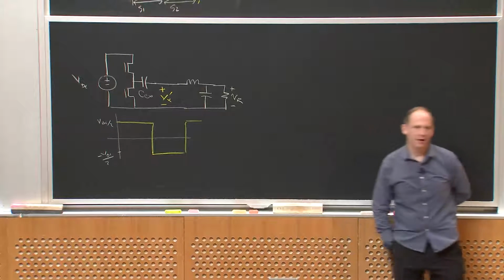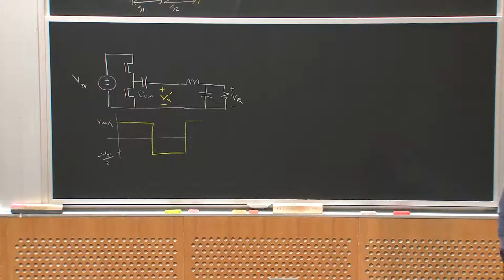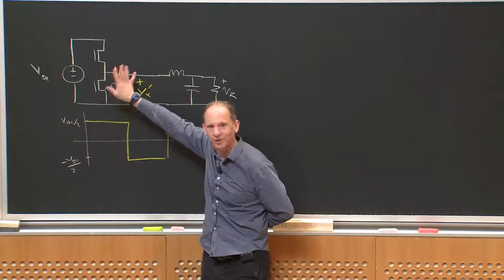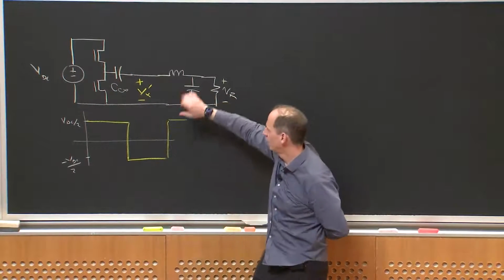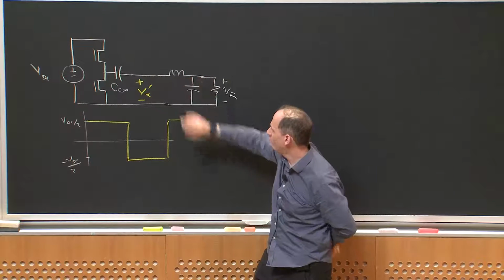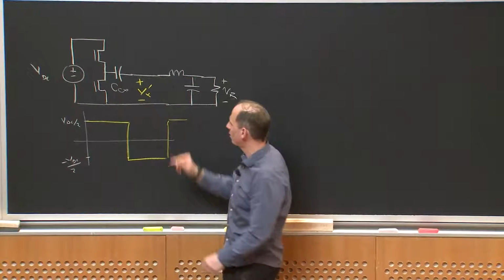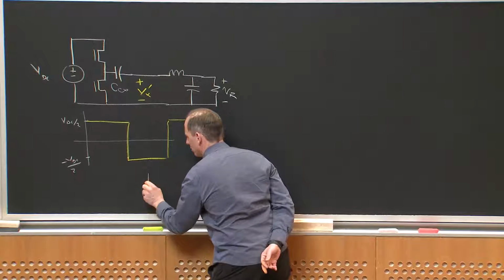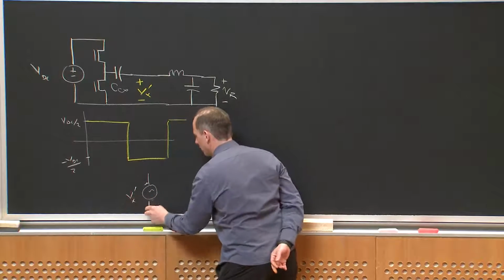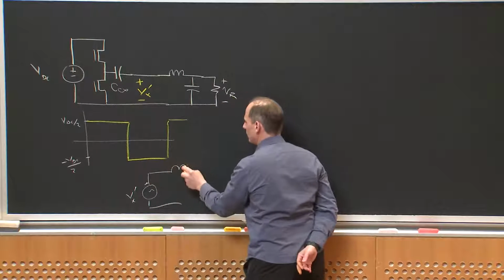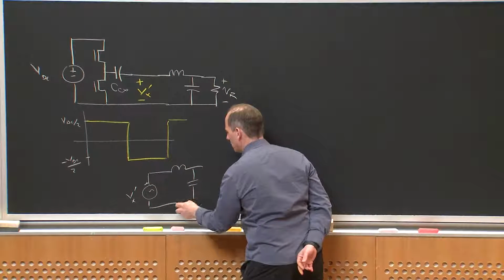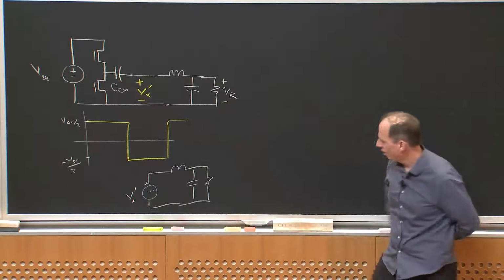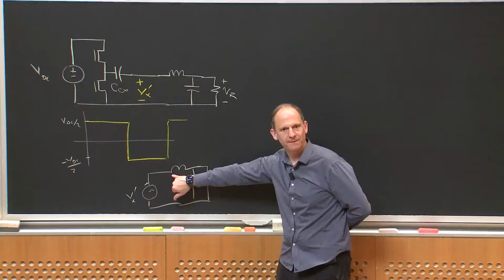This would be called a parallel resonant inverter. Instead of having a blocking capacitor here, I could have done this in different ways, including using a full bridge, et cetera, but I just want to illustrate this. Now, why is this a parallel resonant network? If I thought of Vx prime as a voltage source, if I make Vx prime 0, L, C, and R here are in parallel, right?